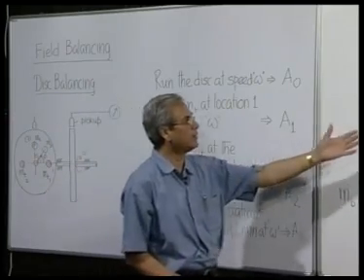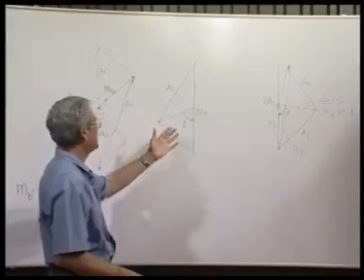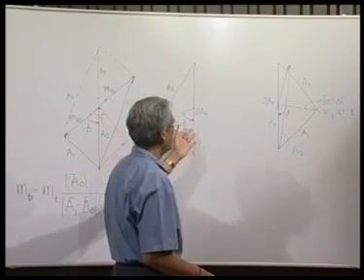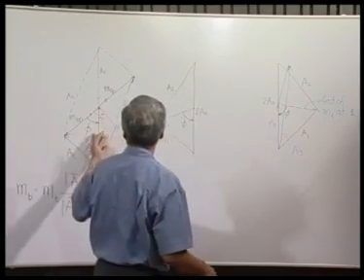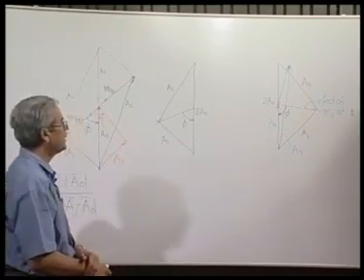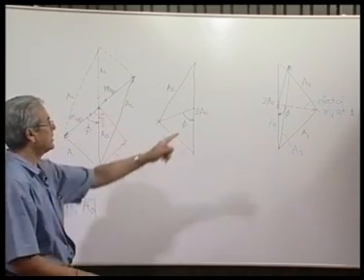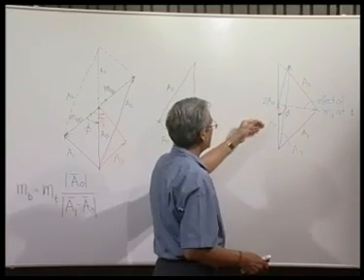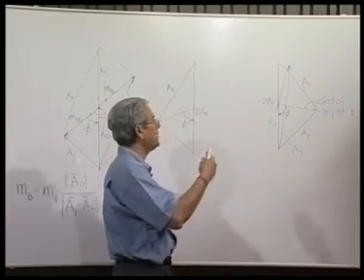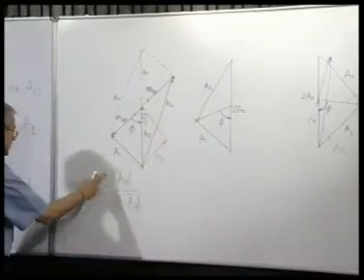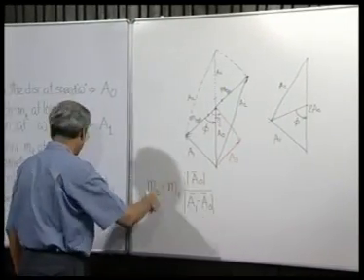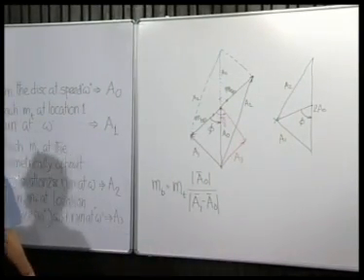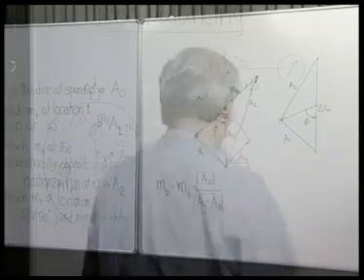With that you can draw the figure, it will be either this or that, depending on the magnitude of A3. If it is large, that is the configuration, and then you have to rotate your trial mass in the clockwise direction by an angle phi; the magnitude will be given by the same relationship, but the position will be different, it will be here.